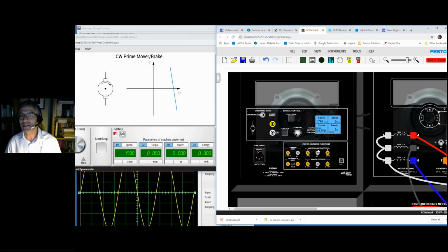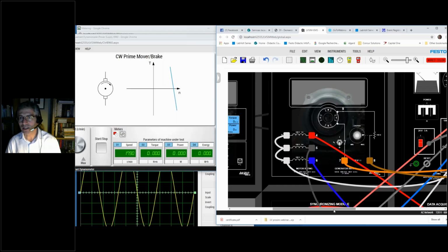If I was applying a specific torque, which is compensated by the counter torque of the generator, which is normally the case in the real mechanical situation, and we remove the field, then there is no torque on the generator shaft anymore, and then of course the generator starts speeding up because of this. But in this case, because of the simulated prime mover that we're using, we don't get this effect. Sorry if that's not what you were expecting.